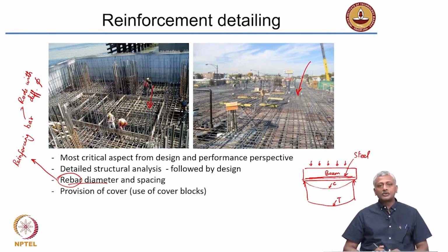Now, it's very important also to figure out how you can protect the steel from corroding. You know that steel left in the environment is prone to corrosion, and that's a natural phenomenon because steel is Fe. The naturally stable condition of any metal is its oxide state, right? So, the Fe will obviously want to convert to the ferric or ferrous oxide states. In such a case, how do we protect the steel from corrosion?